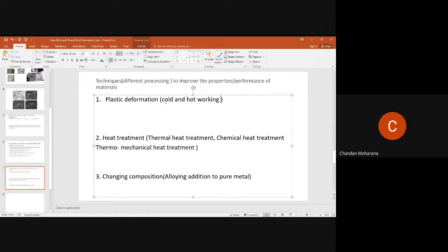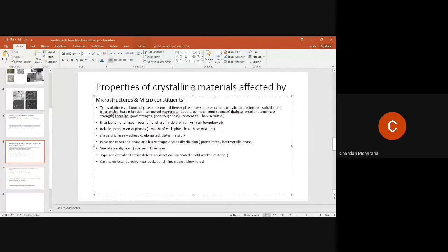Okay, so in which case will you be able to see recrystallization, hot working or cold working, without doing any other treatment? Hot working. Hot working, very good. And that kind of recrystallization is called what kind of recrystallization? Dynamic. It is deforming, a new crystal is generating. Again deforming, a new crystal is generating, right? Dynamic. Okay, anyway, you understand.